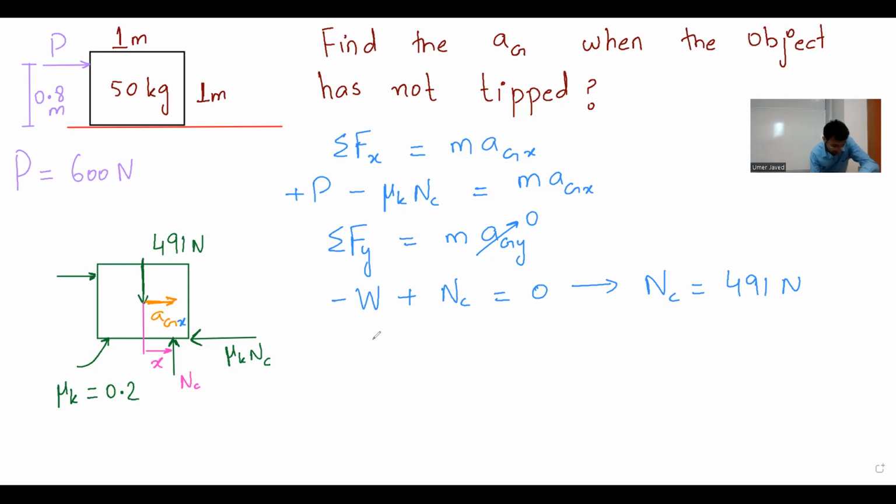So I will say, let's say clockwise moment positive. You can do anti-clockwise if you don't like this. The summation of moment about G is equal to I_g alpha, correct? So what is the value of alpha? In a pure translation problem, for this expression, it is 0, right?